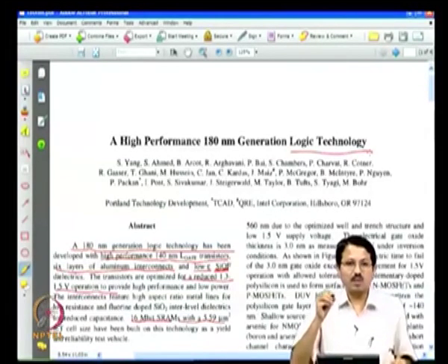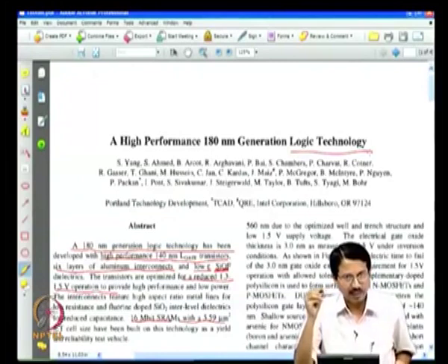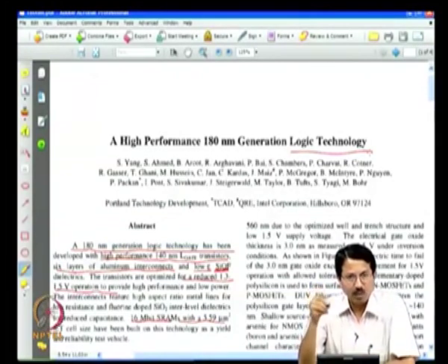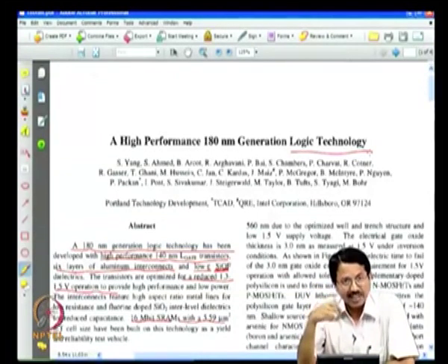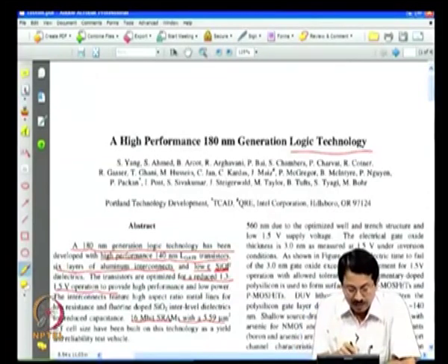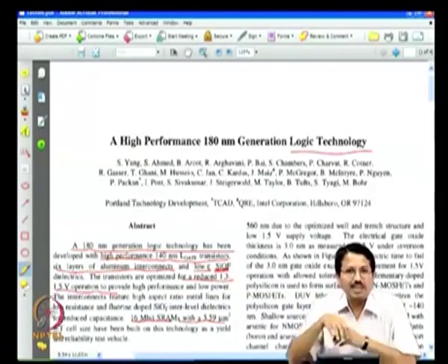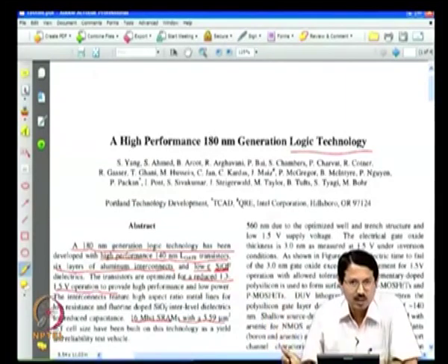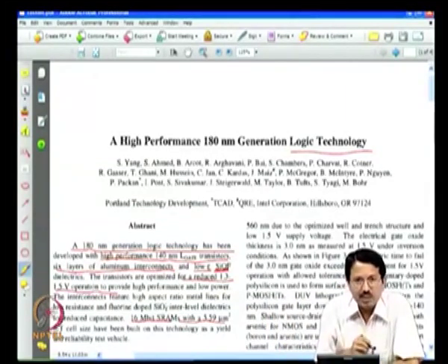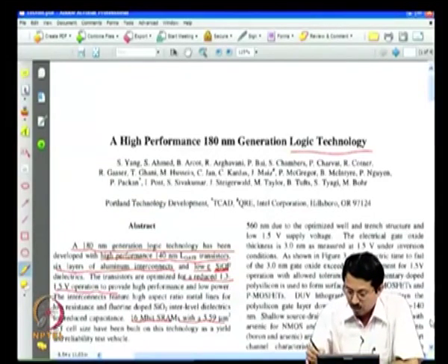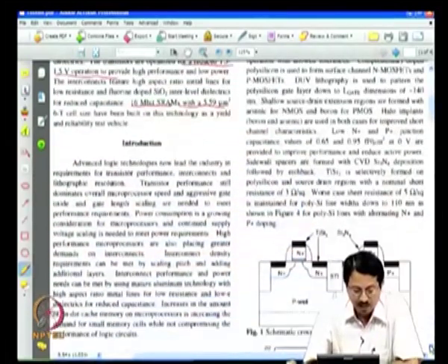Logic technology will be used to build microprocessors, which are very high end logic chips, but microprocessors on chip will have cache memory, right. So, these SRAMs will be used for cache memories in the microprocessors. These are not going to be standalone SRAM chips to be sold. Okay. So, they have been able to demonstrate that SRAM circuit can also be implemented using this technology. Okay. So, let us then just go through some key highlights here.